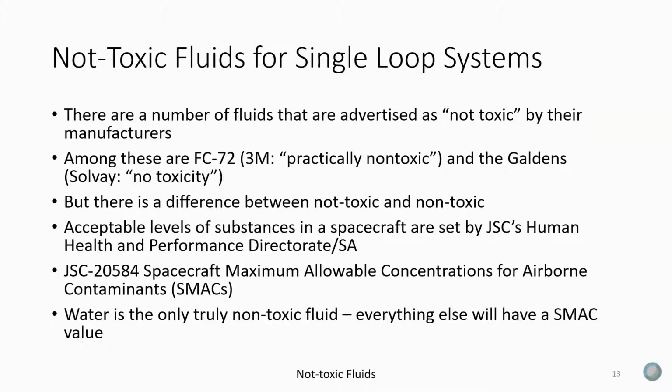Apollo used water ethylene glycol, and they did use a stagnation radiator, but the mixture of water ethylene glycol they used was a eutectic mixture, so it didn't actually freeze, it more kind of slushed. So they never got to a point on the radiators where they stopped flow. The water propylene glycol does actually freeze.